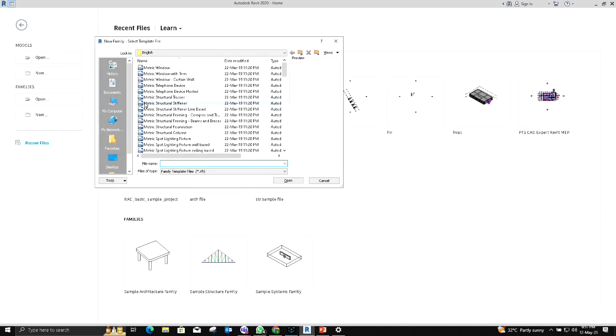this one. Here are some generic templates for that also. Here, this one is templates. Okay, Revit family templates. You can take any template and make any family as you wish. Like if you have an AHU of a size which you don't find in your Revit default families, like 100 by 100 AHU, you want to make a new one, so you can make it from here.